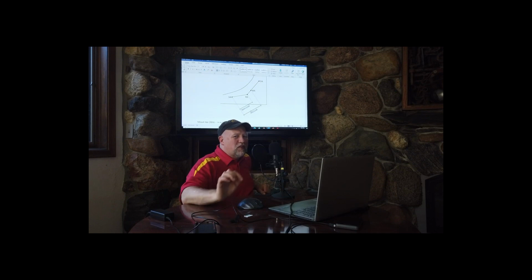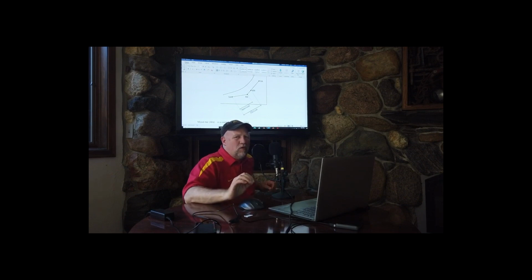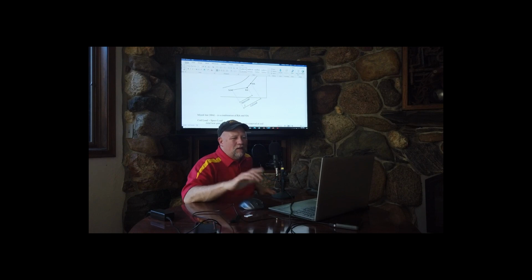We don't want to oversize our air conditioning units, though. Just as a warning, it's okay to oversize heating systems. It's not okay to oversize air conditioning systems. If you have too large of an air conditioner, it'll sit there and turn on and off and on and off, something called short cycling. And you will substantially reduce the life expectancy of that air conditioning unit. You will also not get really good humidity control of your space. And I'll illustrate that with a few examples later.